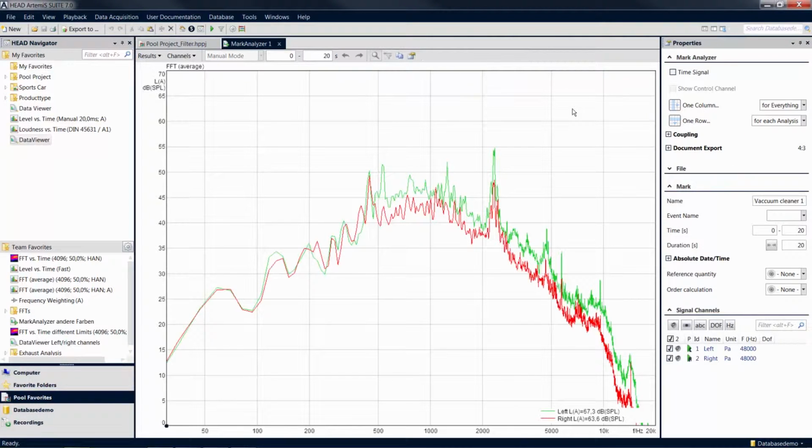In the FFT analysis diagram, we can see some peaks distinct from the rest of the signal curve. We now want to reduce these sound components to smooth the spectrum using the playback filters. To play the sound, simply click on the playback icon in the toolbar.